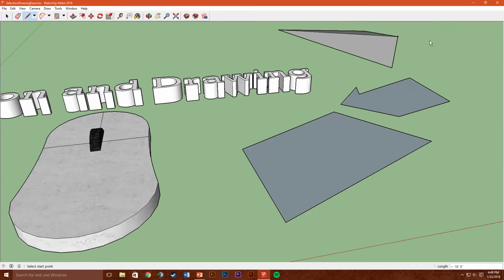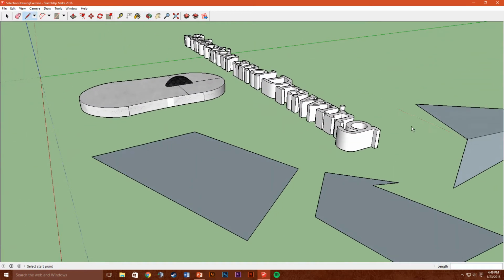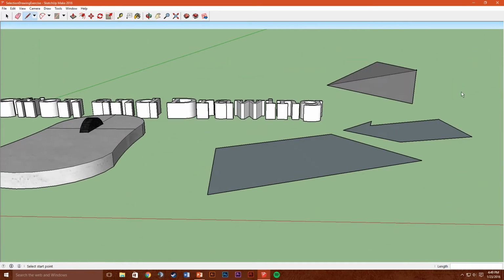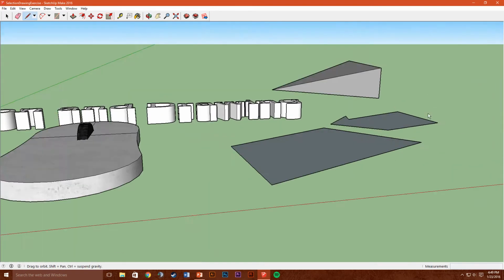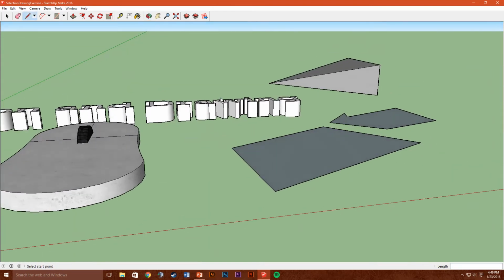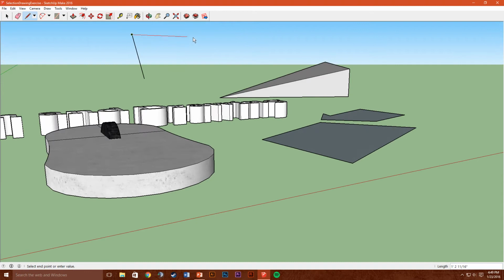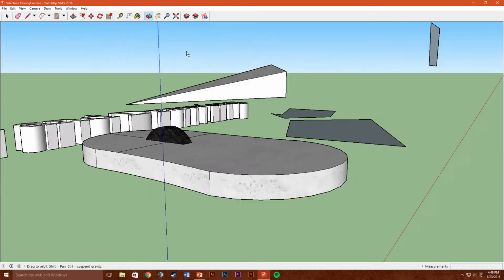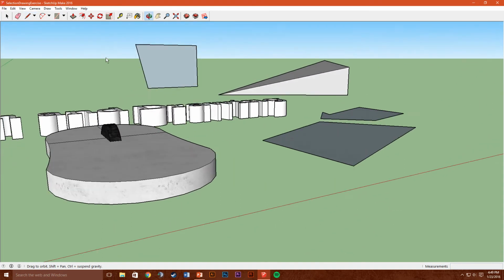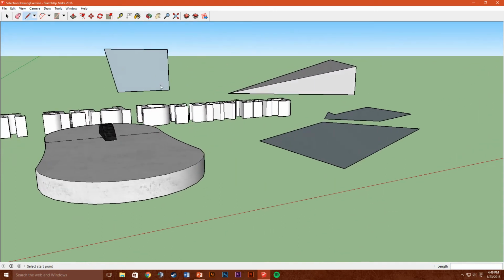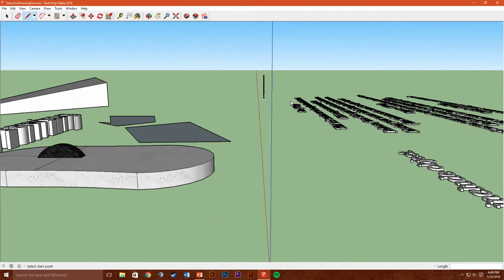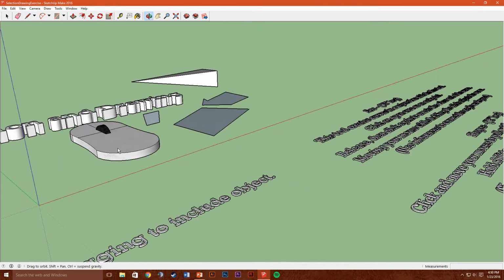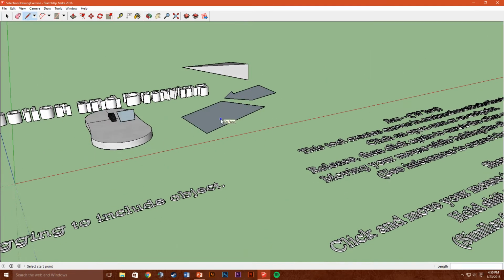Line tool is also something to be cautious with whenever you are using it, especially if you're going to use it in midair, not attached to something, as a freestanding object. You never really know if you're clicking up in the air if you're going to get a flat surface or where it's even going to exist. See, I assumed that it was going to be out in that field out here, and then I rotate around it, and it's floating up above this mouse. So you got to be really careful with the line tool.